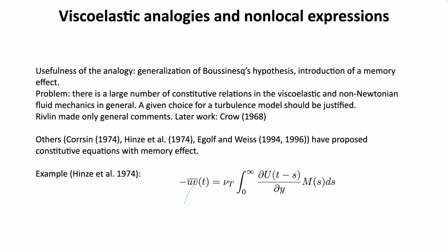Actually, there are benchmarks for flow in a duct that are very classical, in which the Boussinesq hypothesis fails to predict the secondary flow, like at the corners. When you include either a nonlinear approach or Reynolds stress tensors, they do manage to capture what is observed as a major feature of the duct flow in the experiment. I don't know if this kind of approach can. I think they do actually perform well also in a duct, the approach you just showed, right? Duct flow, yeah. Okay.